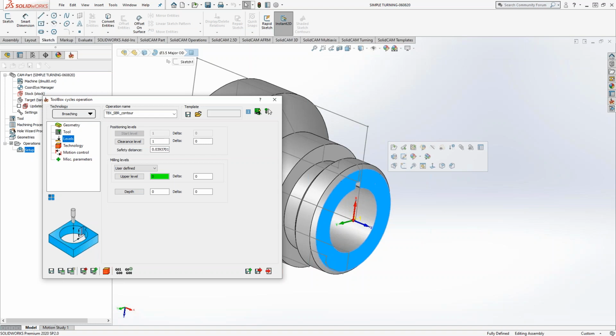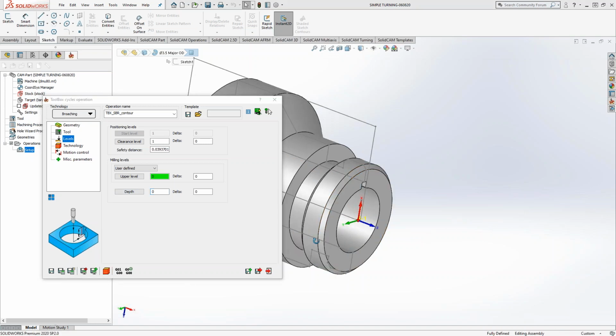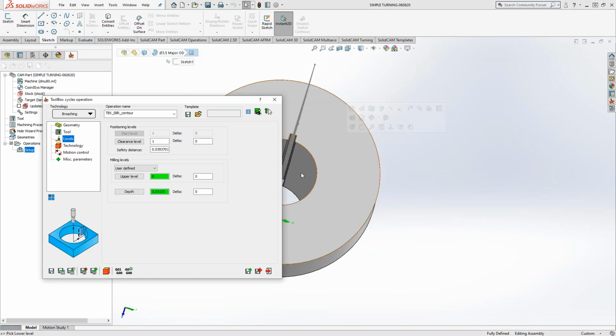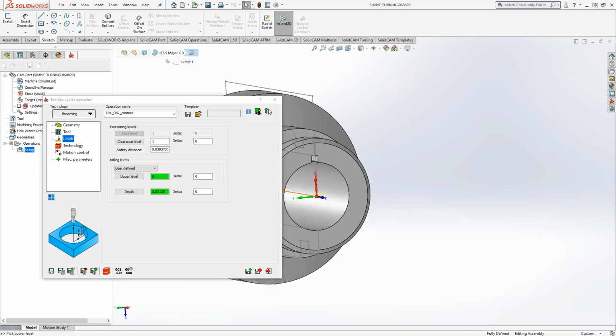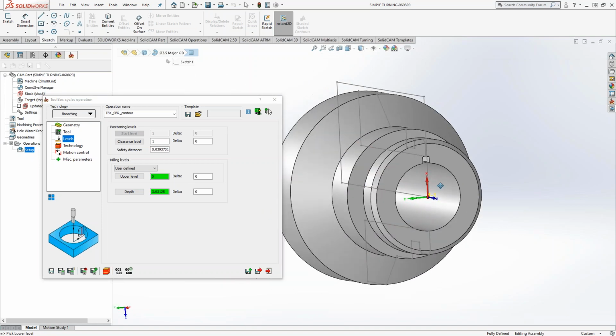The difference is one starts from the target definition and one is literally from that face that I chose. So if we go back to the original model and make a change in the size of the model, the locations of any kind of faces, this toolpath will always start at that face. And for the depth, well, it looks like it goes all the way through. So I'll click on the back side of the part. Now, if that's even possible, yeah, probably not, but we'll see.